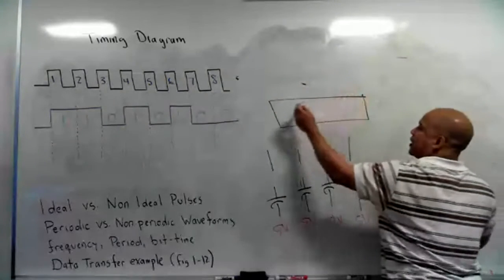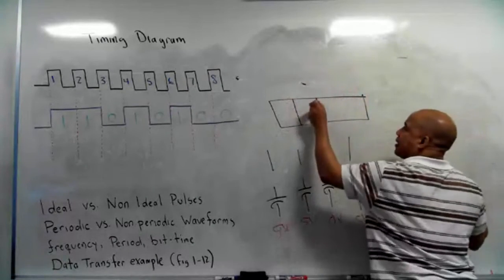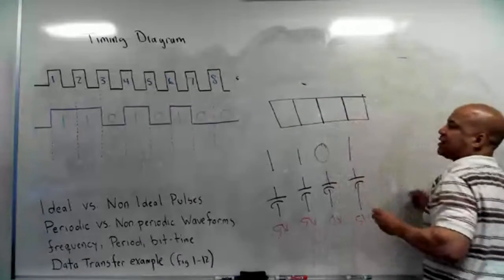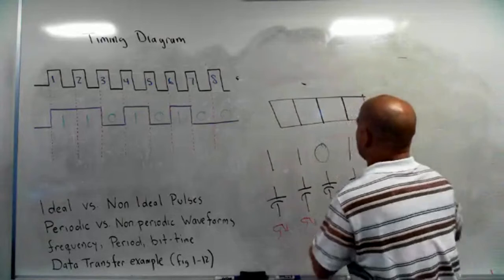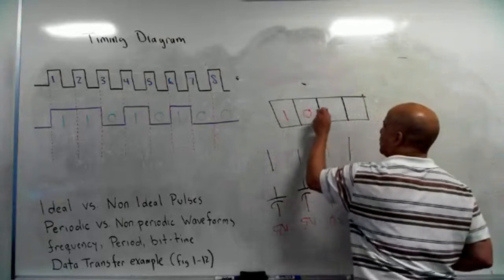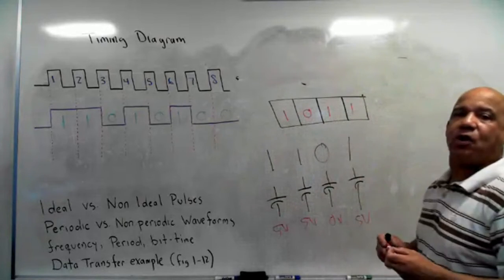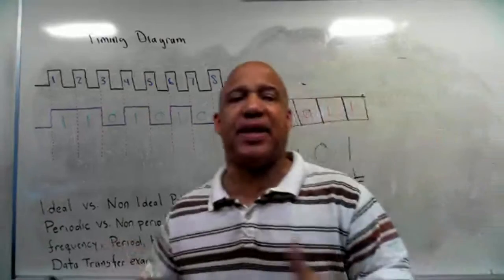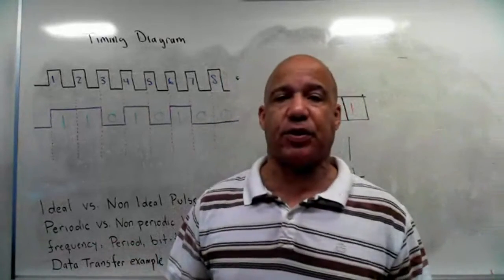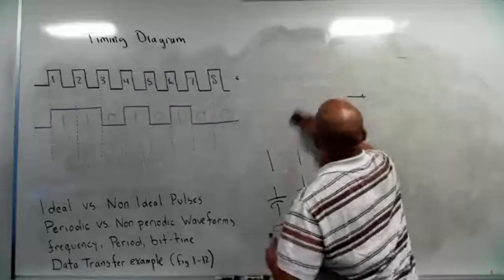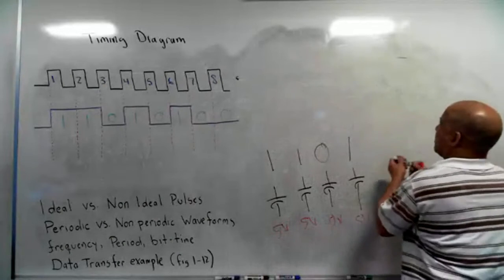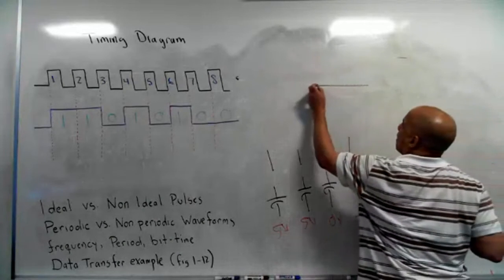So a 4-bit shift register is just a container, and it has these 4 spaces that I can put bits in. So I can put ones and zeros in here. Might put something like this in there. The question is, how do you get those bits into and out of the shift register? You go buy this device, and at first it's empty. Let me redraw this. At first it's empty.